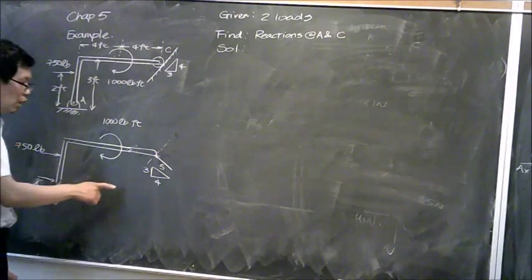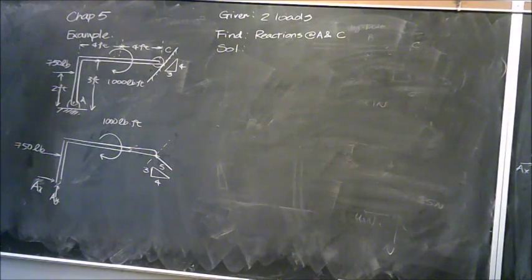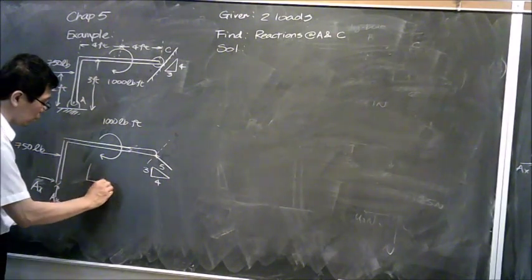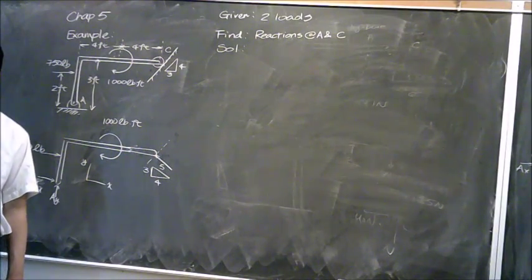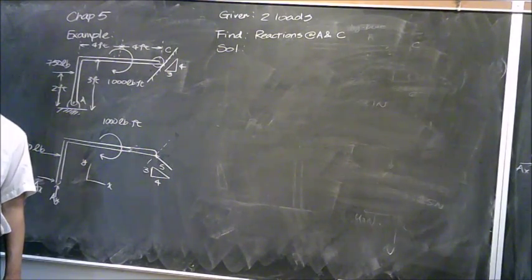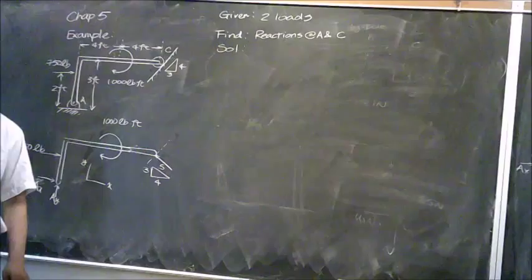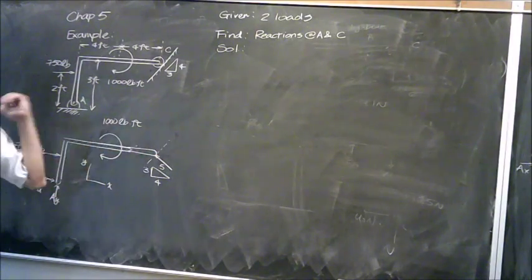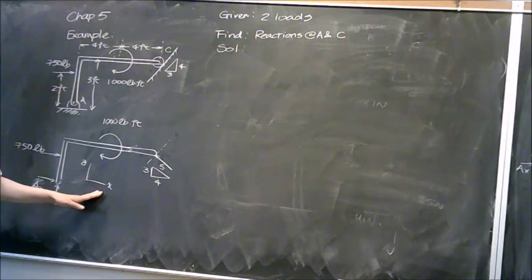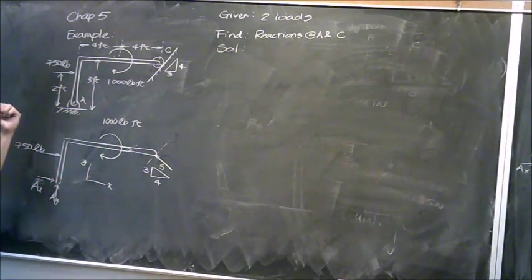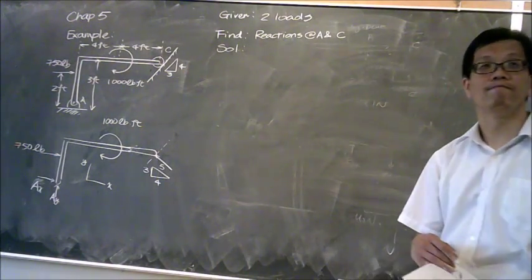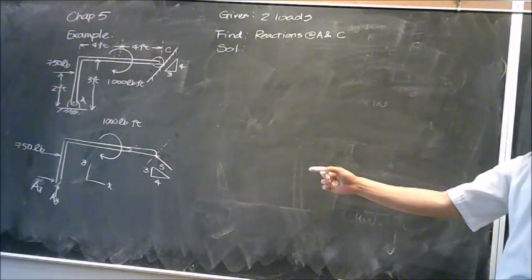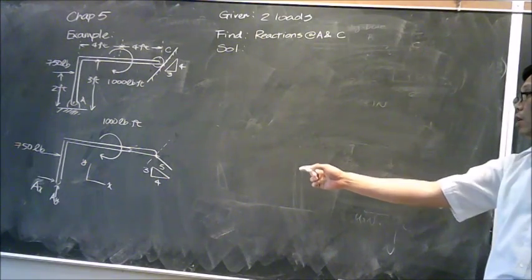Okay. So after you finish your free-body diagram, there is one important thing I would like you to do. That is to draw the direction of X and Y. In this case, you ensure yourself which direction is positive and which direction is negative. Because sometimes you might confuse yourself and not know whether this is positive or this is positive. So if you have a reference coordinate over here, you always ensure yourself right hand side is your positive, left hand side is your negative. Does that make sense to everybody? Questions so far? Is that clear? Everybody understand how I draw the free-body diagram?